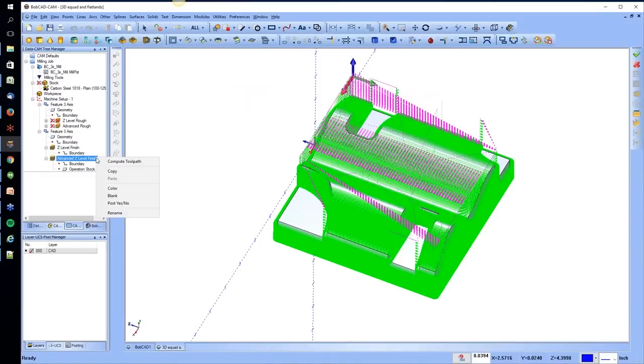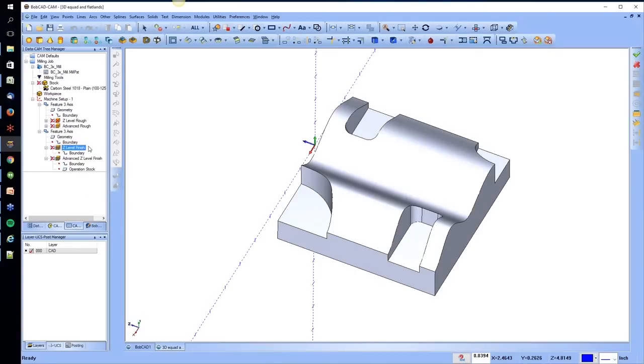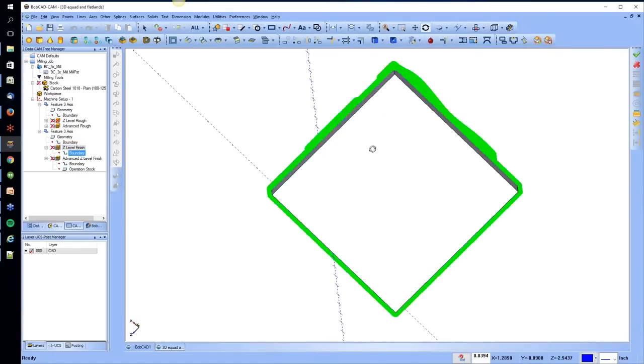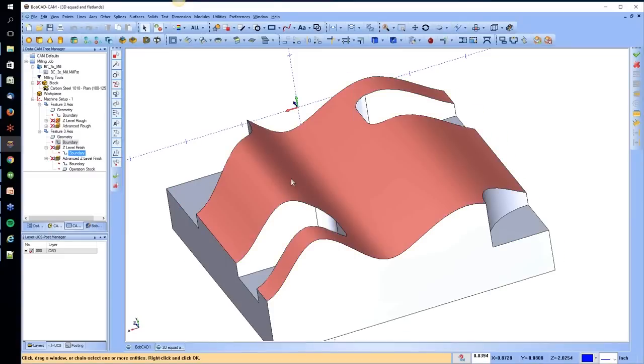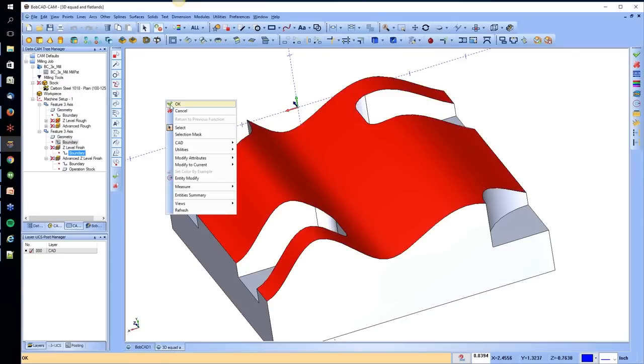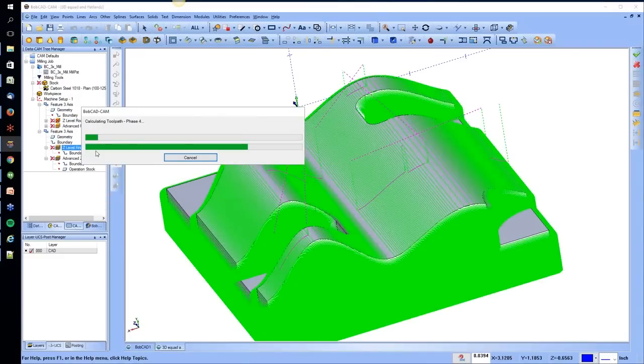All right, so let's go ahead, blank out the two, like so. So here's the Z-level finish. Now, it's doing a pretty good job. Problem, first off the bat, bigger scallops up top. It's a projection of a toolpath going down on the surface. It is cutting everything. So let's go ahead and boundary it off to only touch the top. If we go to the boundary option, reselect, pick the boundary, hit OK, and then recalculate that toolpath, and we'll leave the other one without it at first.